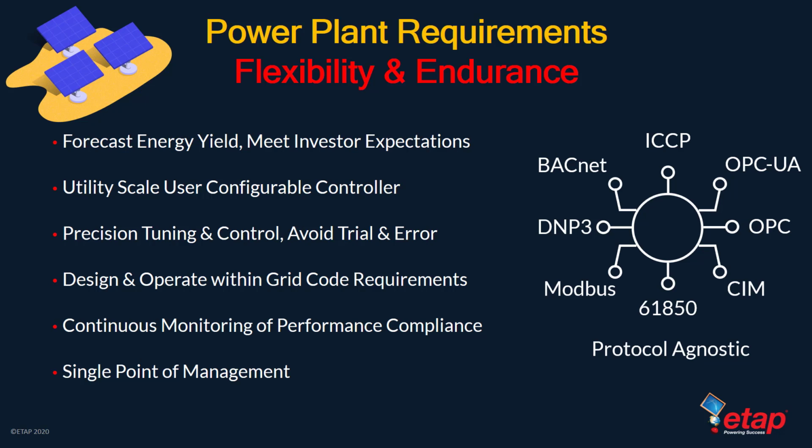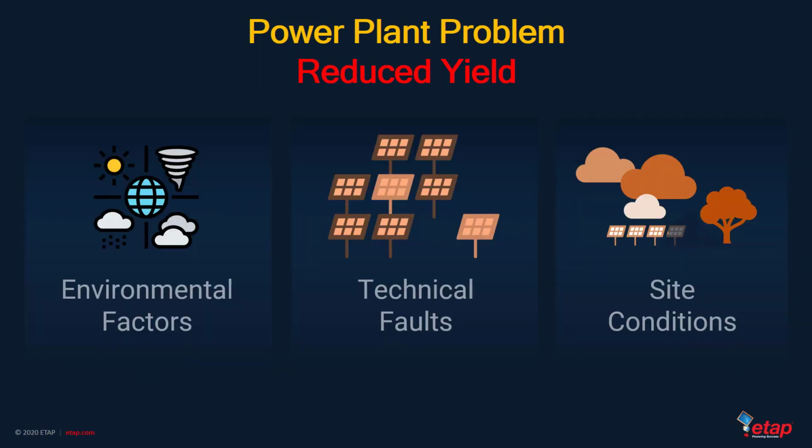An ideal monitoring system allows the yield of the plant to be monitored and compared with theoretical calculations and raise warnings daily if there is a performance shortfall. Faults can therefore be detected and rectified before they have an appreciable effect on production. Without a reliable monitoring system, it can take many months for a poorly performing plant to be identified, and this can lead to unnecessary revenue losses.